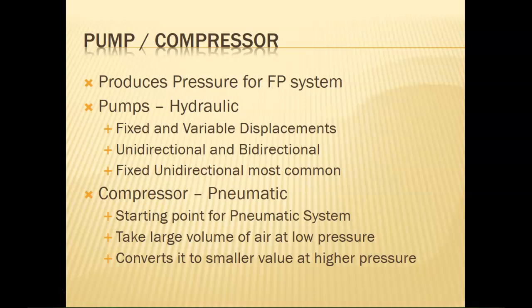So pumps are either fixed or variable displacements. What that means is if it's a fixed displacement, it has a fixed amount of fluid it will push at any one time. Okay? It will never push more than what it can. If you start gunking it up, it will push less. Okay? That's why you've got to really take care of it.